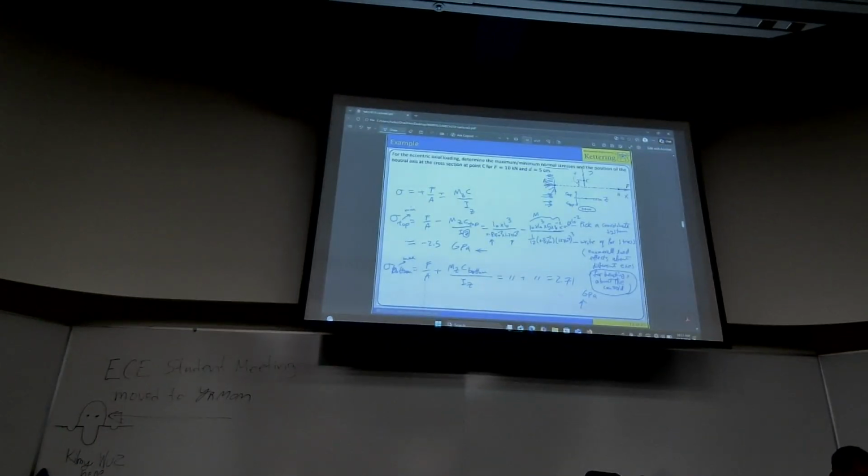All right, so last time we looked at this eccentric loading case, basically axial load with an offset, and we said it induces both normal stress due to axial force, F over A, and due to bending, MC over I, and you guys helped me with calculating these. My feedback to you guys is some of you were very quick in calculation, so great.